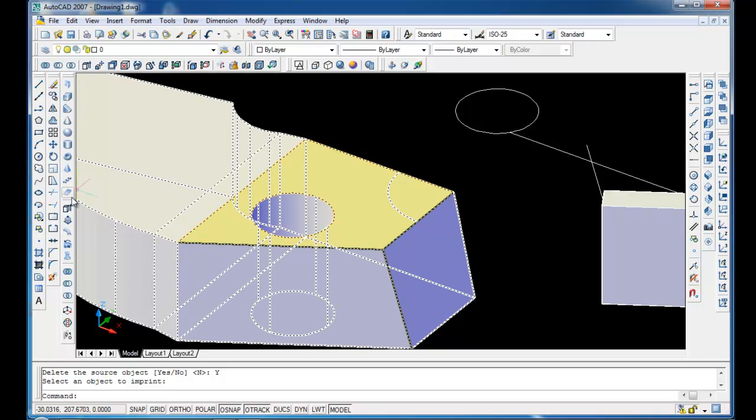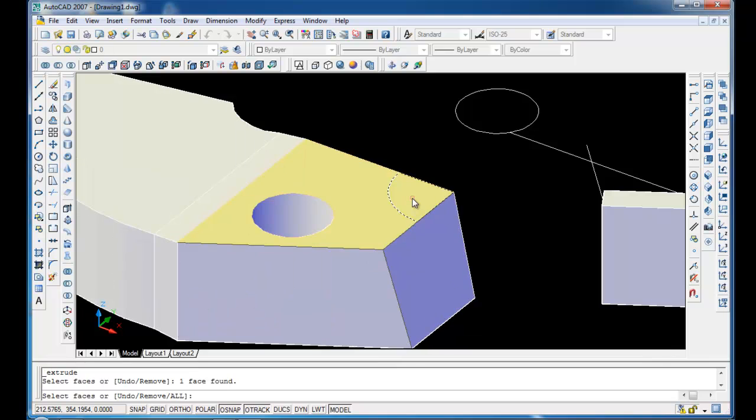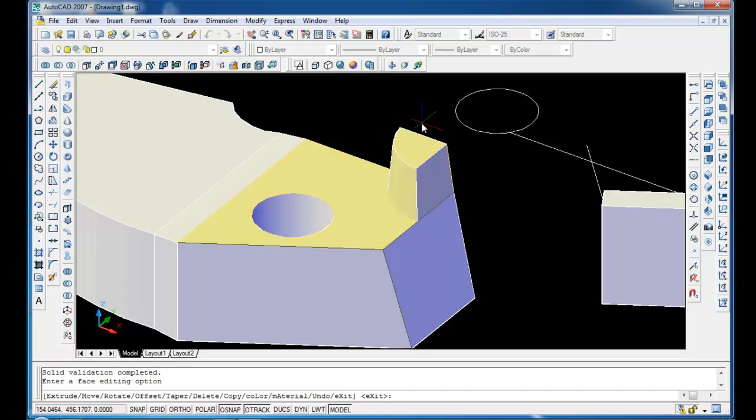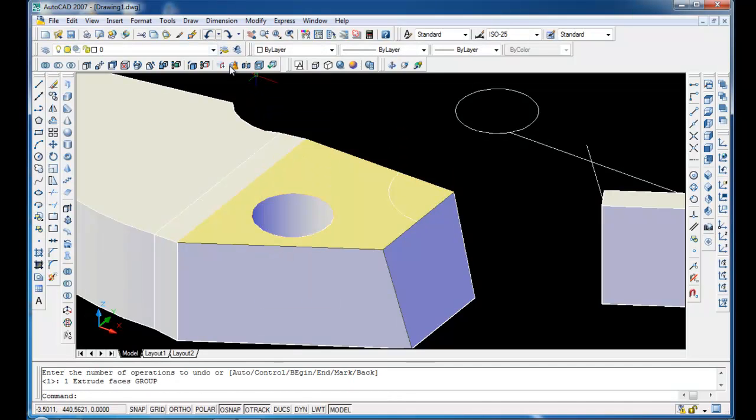Now I can directly go ahead with extrude face on this object with the help of a given height and give a 0.5 degree taper. It means that much area, that is the imprinted area, can be extruded or moved, or used in some other different applications as per the customer requirement. Like this you can go further keeping that object, and if you don't want to have that one, go directly for